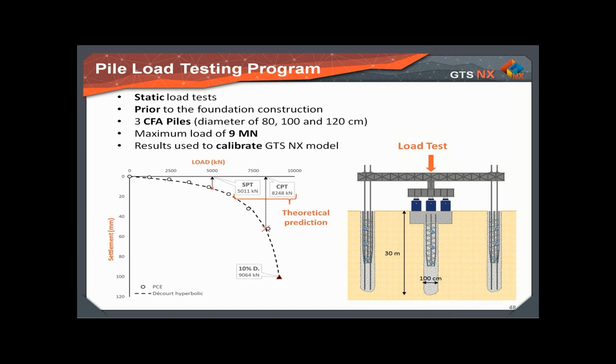As can be seen in the load settlement curve, there is a difference between them, and the prediction of the behavior of the pile based on the CPT is much closer to those measured in the pile load tests, which is mostly explained because of the nature of the test, which is much more technological than the SPT. And in MIDAS GTS NX, the results from the pile load test were used to define the properties of the pile. It is very important to have pile load tests when designing building foundations, especially tall buildings.